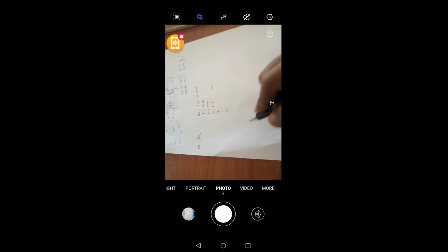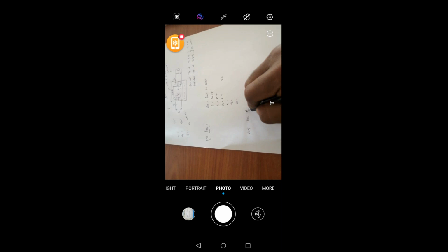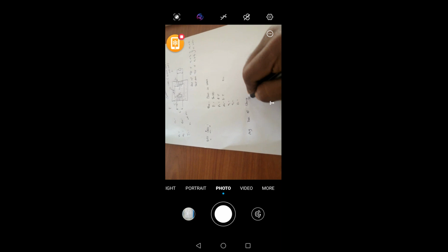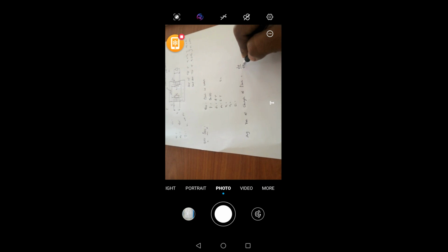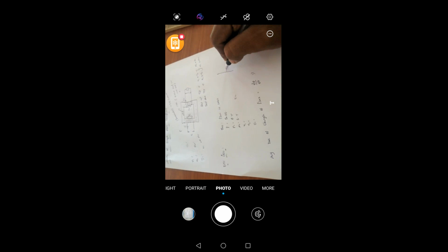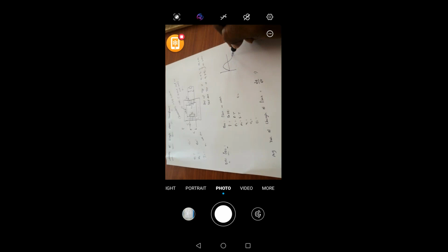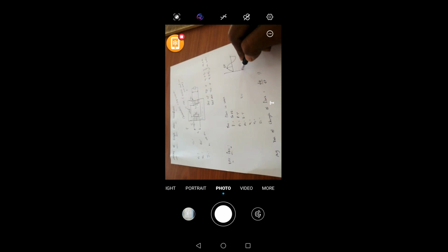That formula is given by the average rate of change of flux, which is dΦ by dt. How do we obtain it? This is the sinusoidal waveform of the flux in the transformer. At this point we get the maximum flux Φm, and if you take this half cycle, the time period is T by 2. If you take this portion, you can write T by 4.